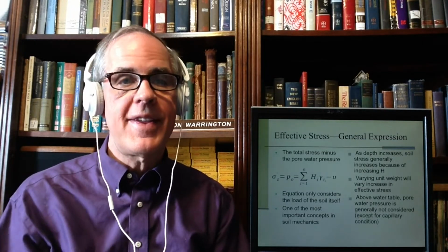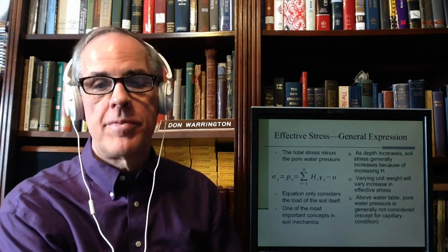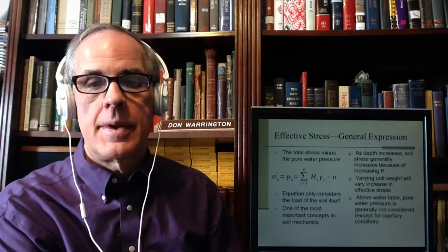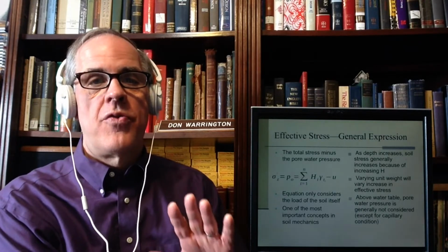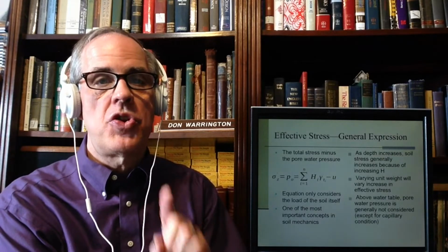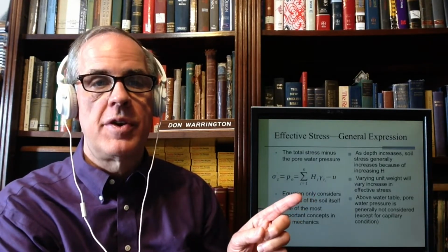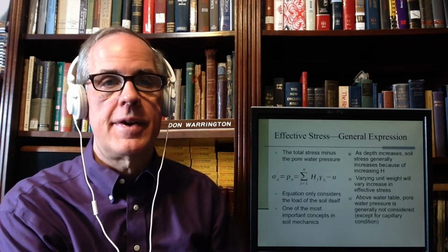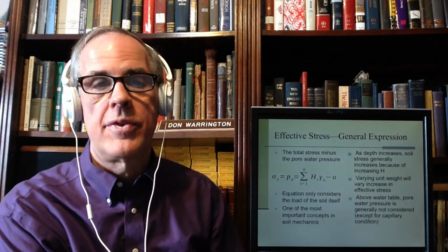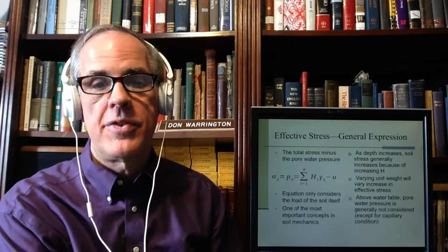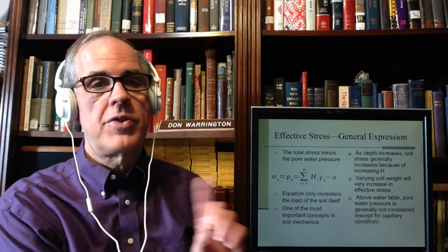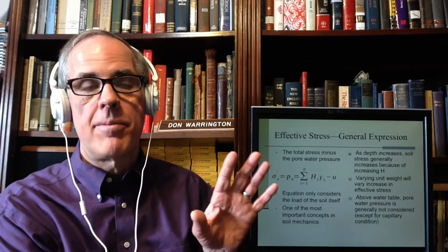But leaving that aside for a minute, the total stress minus the pore water pressure is the classic definition, and for your problems, you should use this definition as your principle. In other words, I would avoid using submerged unit weights unless you're just forced to for some reason. This is the classic way. It's the best way to do it. It only considers the load of the soil itself. We're not getting into all this other stuff that you might put on top of it.